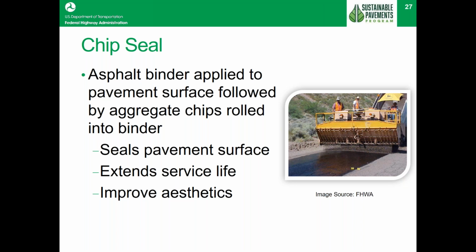Skateboarders really don't like them, because you really can't skateboard on a chip seal very well. And if not done properly, some of the stones can break loose and damage windshields. If that's done properly, you don't really have that big of a problem. Typically, you'll find these kinds of treatments will last for 5 or 6 years at least. In some places, they've actually done quite a bit more than that.